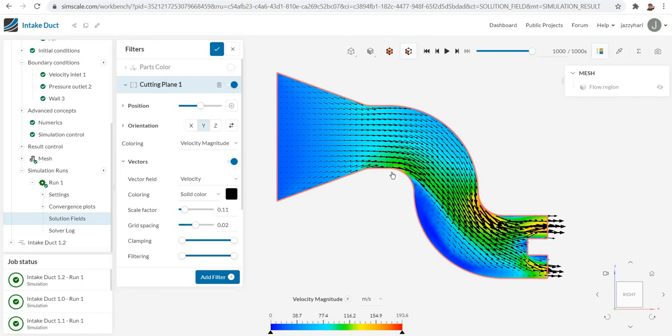To avoid that, the better plan is we want to make the fluid enter in this area. For that what I am preferring is we will make some guide vanes. We will fix some guide vanes here. This bend is actually rotating and moving, so we are making some guide vanes here. Since this cross section is big, the fluid is not coming to here. So my idea is to put some guide vanes here, and after making, we will again go ahead with the analysis and see how it affects the flow.